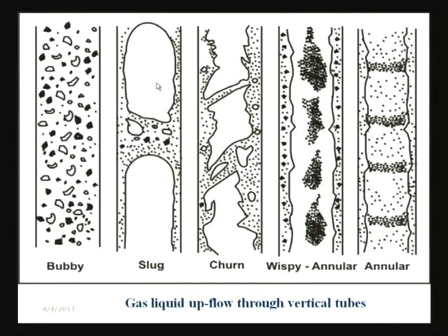Next we come to the churn flow pattern, which is the least understood, least studied flow pattern. I should say there is plenty of scope to study churn flow for the time being. It is a totally random, chaotic, erratic mixture of two-phase flow, not very well understood. And after that again we get the annular flow pattern, which is a very well ordered structure with a gas core and a liquid film. So, these are usually the four types of flow patterns which we encounter in a vertical tube for unheated conditions.